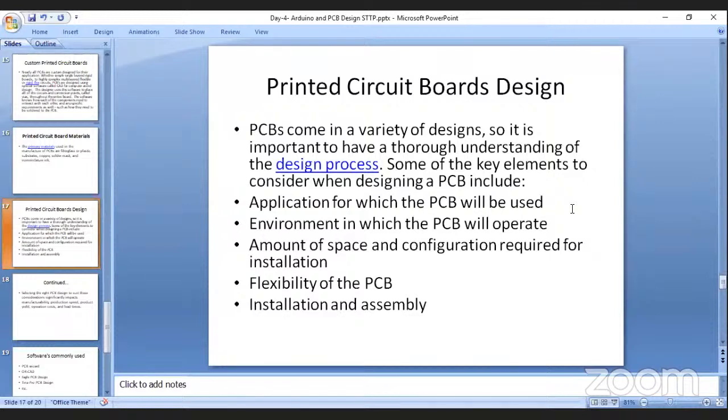So it adds different things to this, because it is a drone, so it should fly. So the PCB should be lighter, which means the area of that PCB should be as small as possible. So that point comes to my mind, right? While designing the system, you have to take care that your PCB size should not be more than required for your drone size, because it requires more power to lift. If the weight increases, then more power will be required to lift the weight.